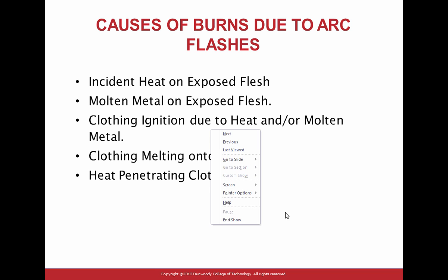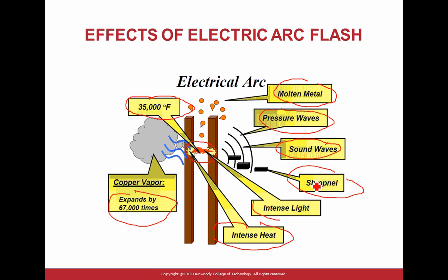Any comments, guys? Questions? The other thing is to point out the copper vapor. That's why the face shield, because what's the first thing that happens? You inhale it. A lot of the burns you get will be in your lungs because of that vapor, and that's why a lot of those have face shields to block it. Absolutely. You go higher than category 0, you're looking at a face shield to protect you. So it's a bad situation.